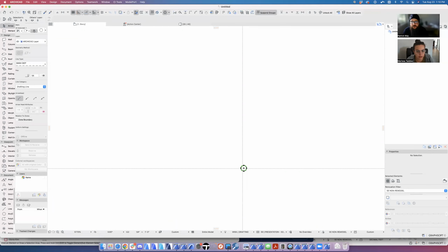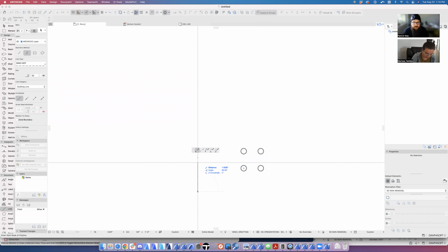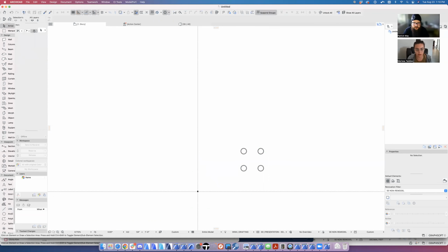Then if they're, say, 3/4 inches on center, you don't need to create the whole array. You just need an offset like that. And then a lot of times I'll create another line and make that like a 64th of an inch, because you do need this to tile.